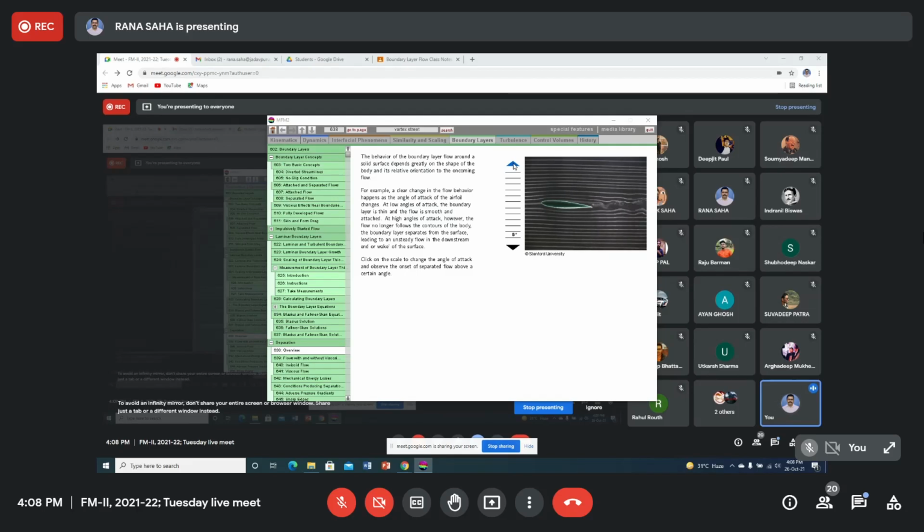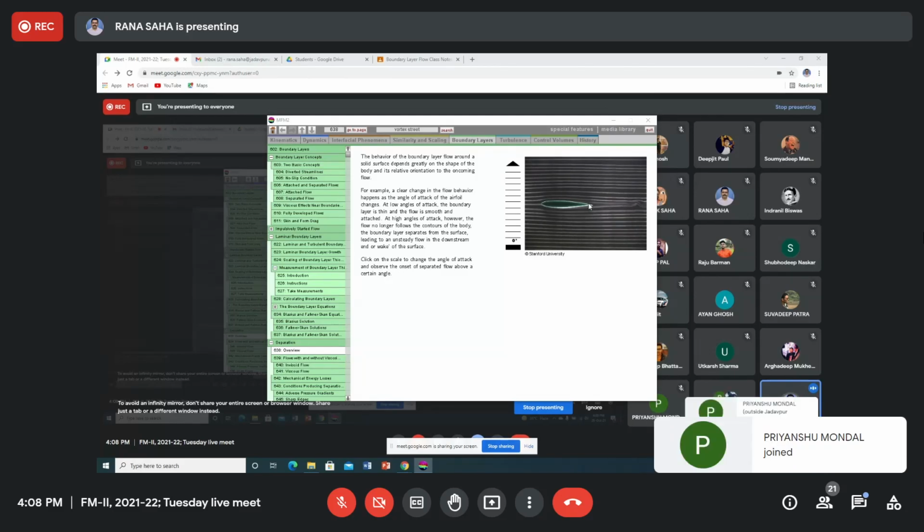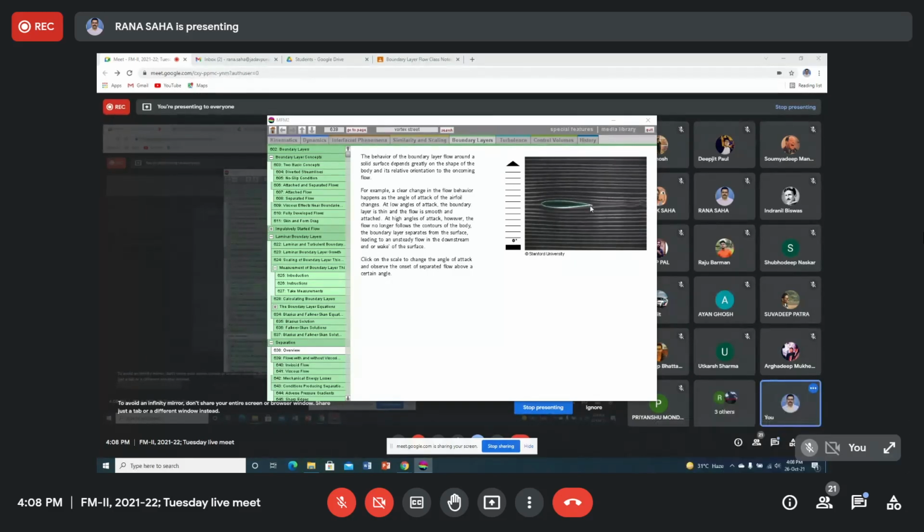Okay, 5 degrees, then 10 degrees more. The inclination with respect to the direction of flow is being changed. This is the wake region now, and as you can observe, the boundary layer separation point shifts. Initially, when it was 0 here, typically you have these two as the separation points, and this is the wake region.